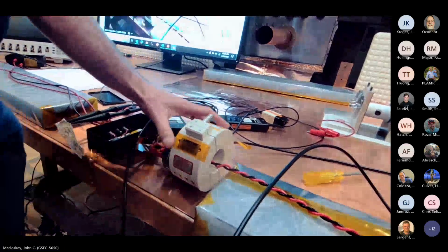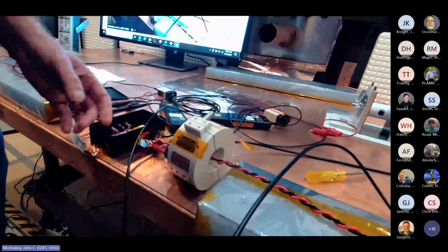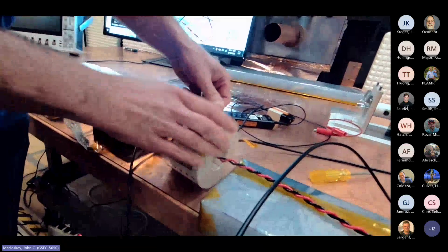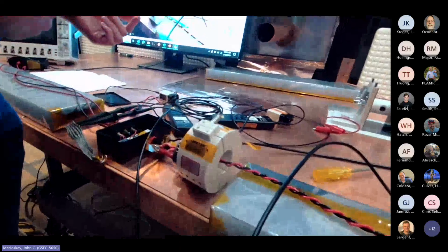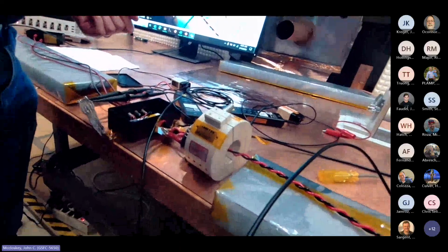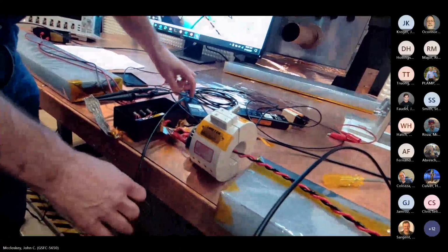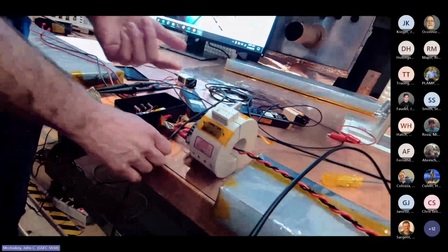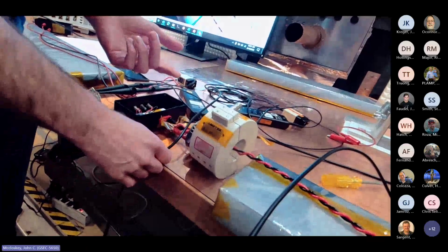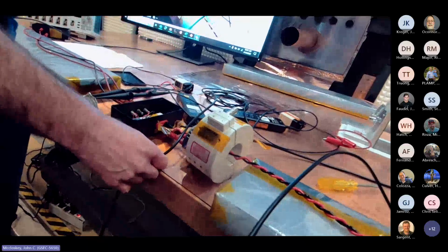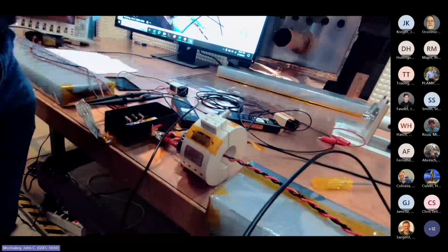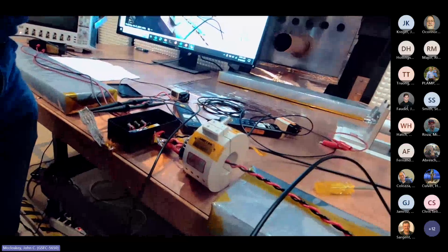Now, strictly speaking, you could just inject your pre-calibrated levels, or in this case, your constant signal generator levels swept across the frequency range. But it's good to have some way of monitoring that you are actually injecting a signal, right? So, what the current is telling you is less important than that you actually have some indication that you're injecting something.